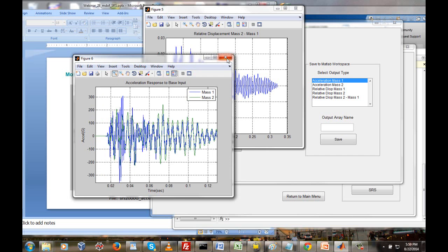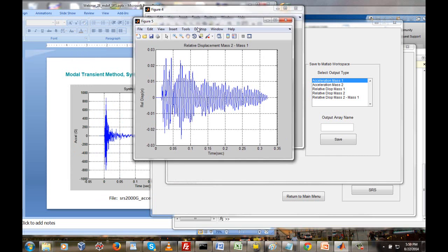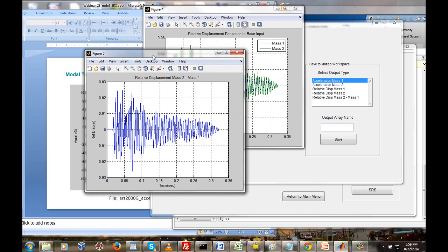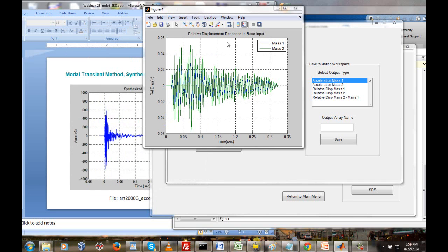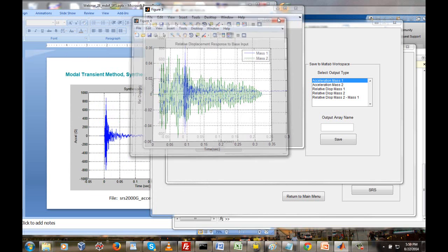200 hertz. Then we could also take a look at the various relative displacement plots, and that could be useful for evaluating the spring deflections, or if we had isolators, making sure the isolators could withstand that deflection. Or there are ways of taking a relative displacement and converting that to force or stress or strain. And we're going to save that for a future webinar.